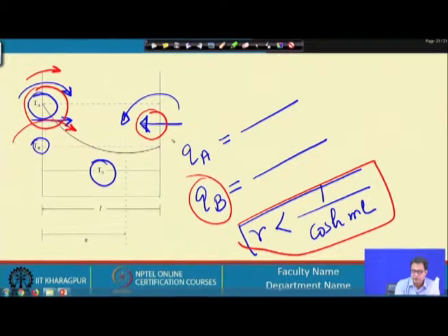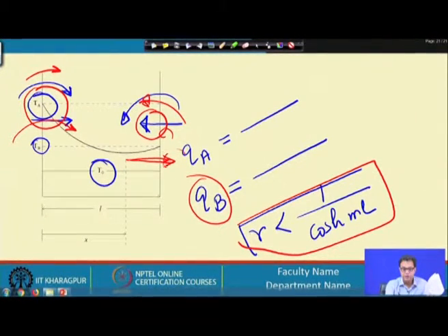So, instead of heat going from the wall to the fin, you will find that the fin is giving heat, the fluid is giving heat to the wall. So, this is in contrast to the earlier situation, and it will lead to a kind of direct heat transfer from this wall to this wall, bypassing the fluid stream, and we often call it as the